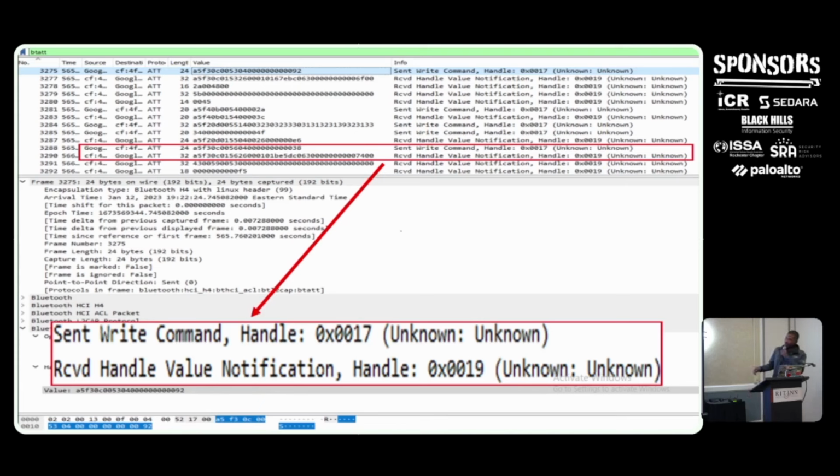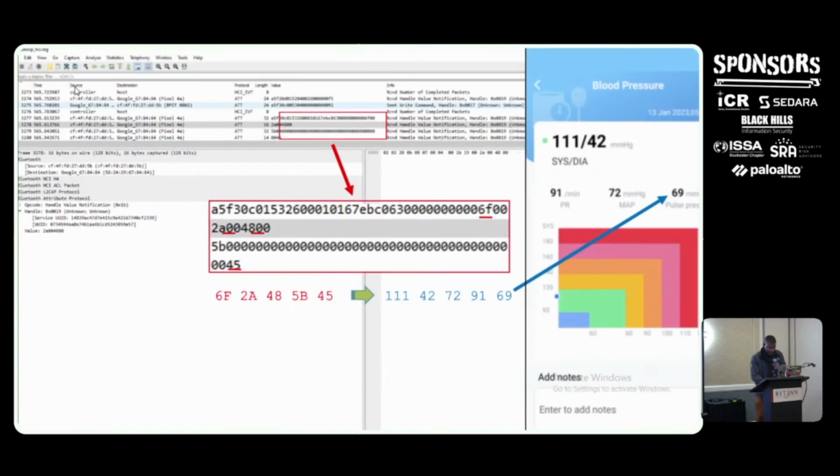The application in question, or at least the vendor, makes at least six products, so there's a lot of code meant for different devices. We'll go over that in a second. But I just wanted to get you looking at the Wireshark PCAP. I don't know if you can see in the upper left-hand corner, I used a filter called BT-ATT, for Bluetooth Attribute. Essentially, by using that filter, you get rid of everything that's not actually over the air. That'll be more important as we move forward. So let's keep this moving.